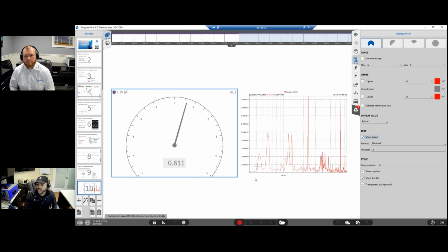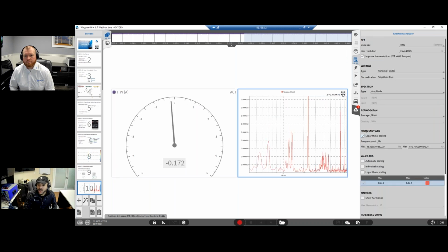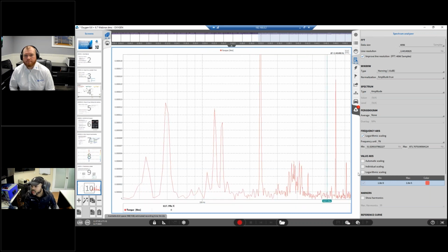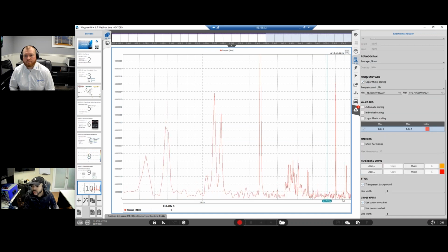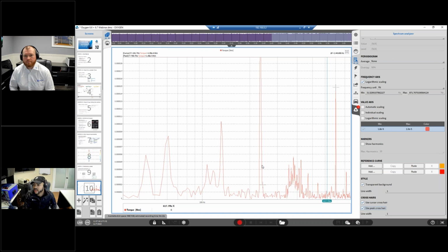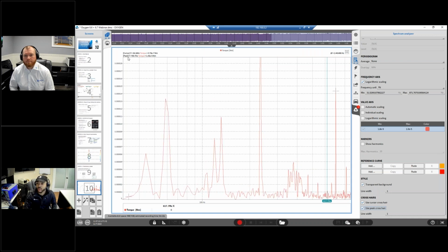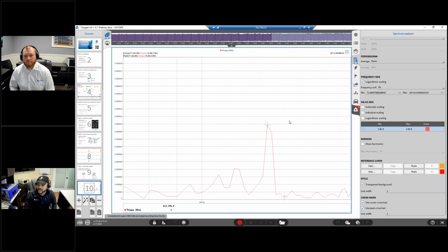As for the spectrum analyzer, right over here, we have a couple signals coming in. And if we hit down over here, use cursors to crosshair, and use peak crosshair, you would get the top peak right at the top right there, and it'll let you know what frequency it's at within the viewable one. So if I were to zoom in, you would get the top peak of whatever's displayed.